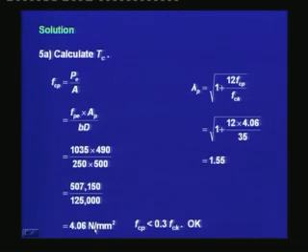Since we are interested in the numeric value, we are not placing the sign in this expression. We have found that FCP is less than 1/3 of the characteristic strength. The characteristic strength is 35 and 1/3 of it is about 12 Newton per millimeter square, and the average pre-stress has been limited to 30% of the characteristic strength.